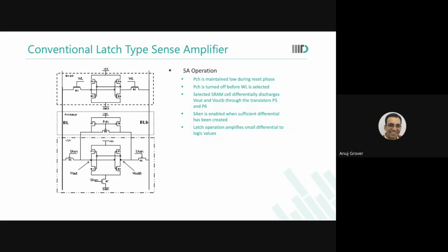Now in amplifiers, what happens is that there is some stack of NMOSs, PMOSs placed together, and you say that I will give a very small input at one particular place. Something like this you do. And then you take output from somewhere and you say a very small differential at these two nodes will lead to a full amplification, or much more amplification, at the output node. That is exactly what we are doing here.